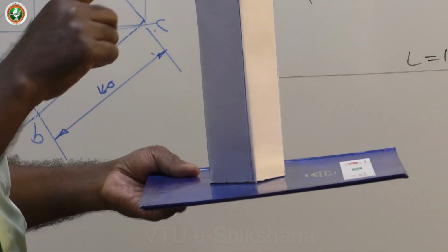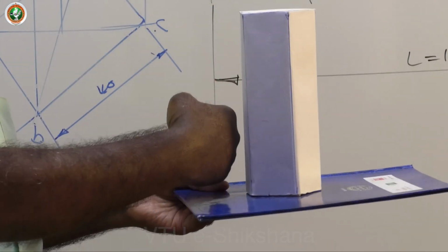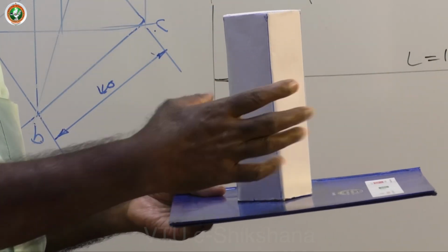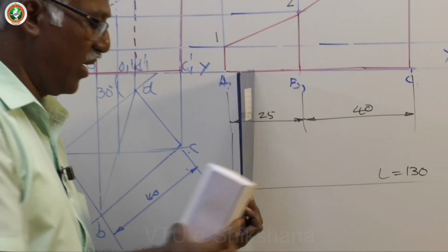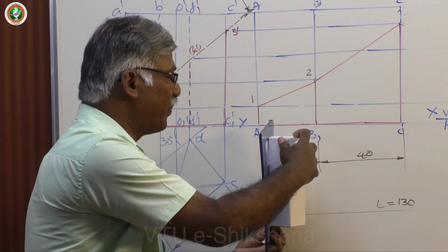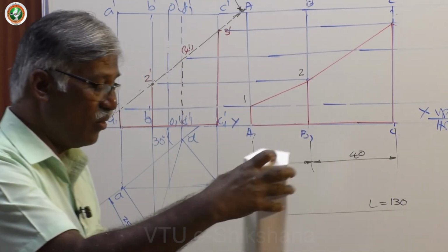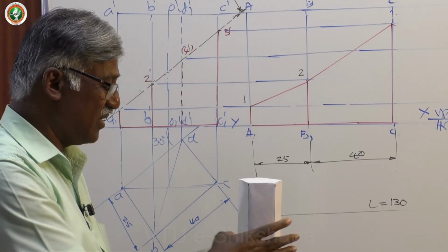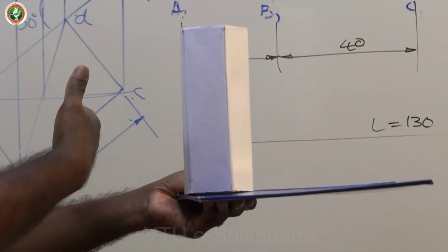See, he says one of the lateral faces, this particular lateral face is perpendicular to VP, so I will take the plane perpendicular to it, and I will place one lateral face. Now you can say clearly the particular lateral face is perpendicular to VP, or instead they may say one of the base edges is perpendicular to VP.